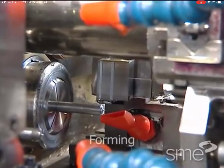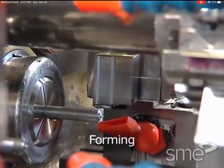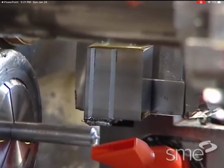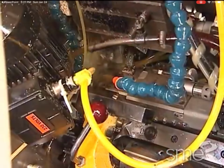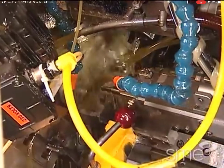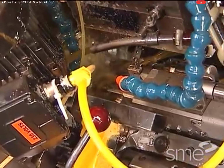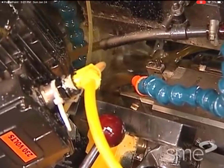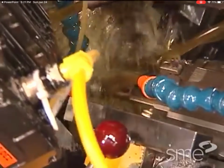Forming is very fast for generating complicated shapes. The tool having the desired form or geometry is advanced perpendicular to the axis of rotation, reproducing the tool shape in the workpiece. Forming is commonly performed on automatic screw machines.